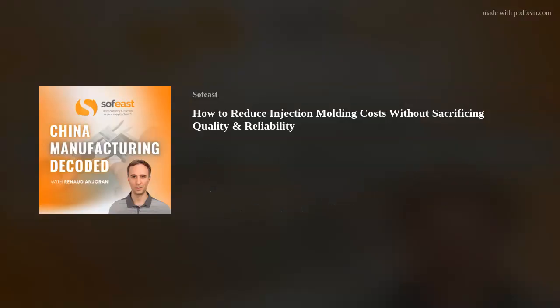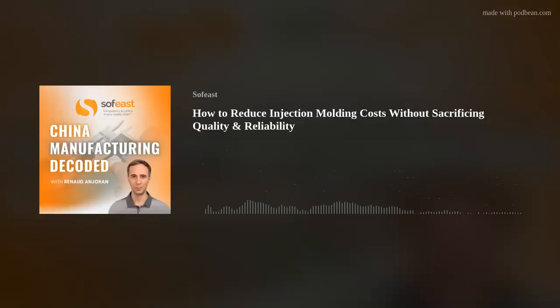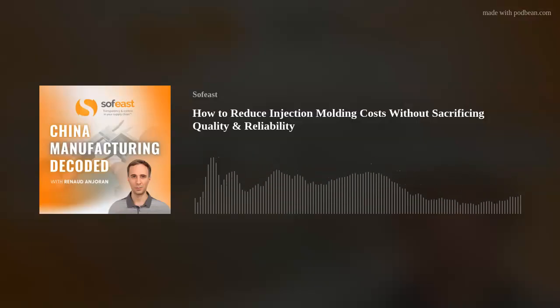He's going to take into consideration the shrink rate of that particular polymer. If you then say, I really want to change it to some other polymer because I now want it see-through, I want a window, so you're going to go polycarbonate or acrylic or whatever, it's a totally different ballgame. It's a totally different shrink rate. In other words, your part's going to come out incorrect because the tool was designed for ABS.